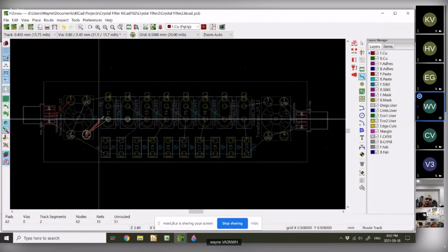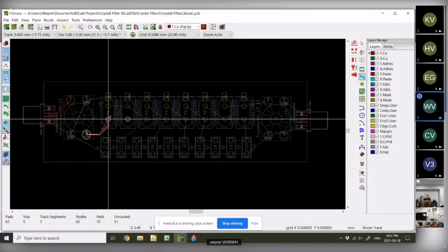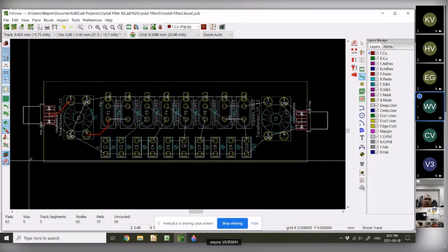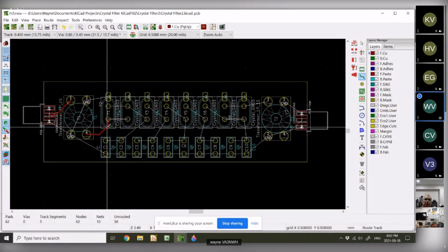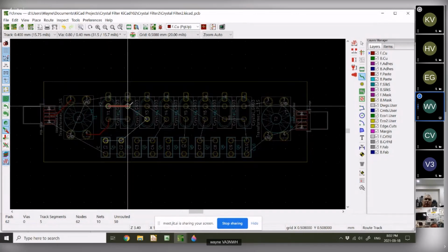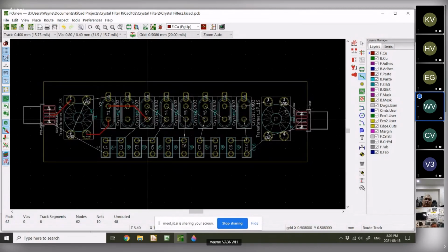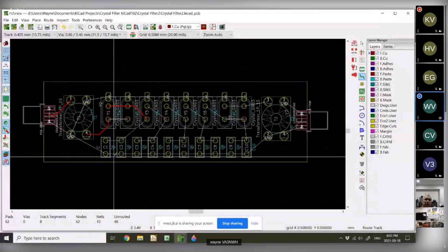You can manually route it. I'm sorry, I should have said that. You can try to manually route it, but it's kind of risky sometimes. But sometimes you have to. It made two bends because it's got a right angle. So it goes, I think that must be 45 degrees. And if you didn't allow enough space for 45, it fixes it for you. Okay. This one will go from here to here. This one won't go, I think, at 45 to here. You will do a little bit of jog and so on. Okay. So drawing the lines is pretty simple if you don't have to move parts after you lay them.